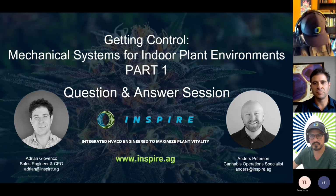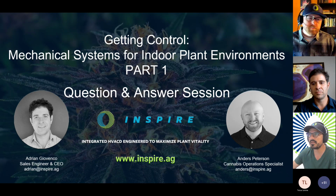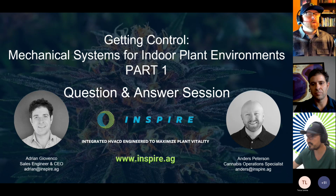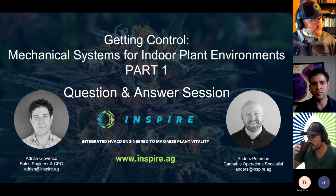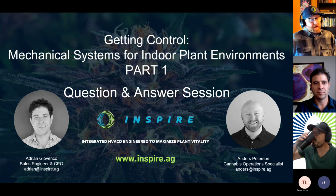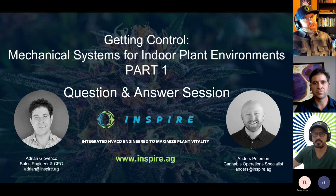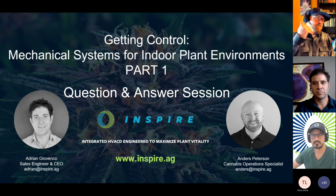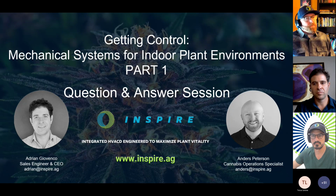Very cool. And I think related to that question is, can your leaf VPD change every couple of minutes within a room with a stable environment? With a stable environment, that's an important distinction. If the room doesn't have homogeneous airflow, then the leaf temperature will vary throughout a space. Essentially, the faster the airflow a plant is getting, the more convective buoyancy flux, and the transpiration rates will increase. So in areas of stagnant airflow, you'll typically see higher leaf surface temperatures.